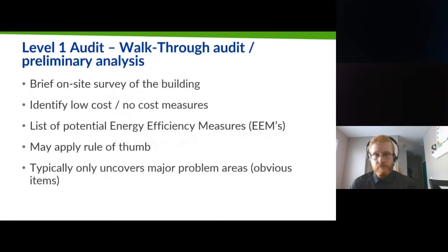So, first audit level is a level 1 audit. It's just essentially a walkthrough audit, a preliminary analysis. It's a very simple audit. It's a screening audit or a walkthrough audit, and it's the most basic. It involves basically minimal interviews with site operating personnel, a brief review of facility utility bills, and other operating data. And as I said, it is just a walkthrough of the facility, and it's all geared towards the identification of glaring areas of energy waste or inefficiency.